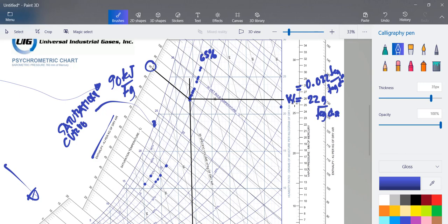Now if you want to look for the wet bulb, you just simply plot it here. So this is now our wet bulb. Wet bulb temperature, starting from here, that is 25, and between 25 and 30. So this is around maybe 27 degrees wet bulb temperature, no? For the specific volume, we have the line here, with the unit of cubic meter per kilogram of dry air.